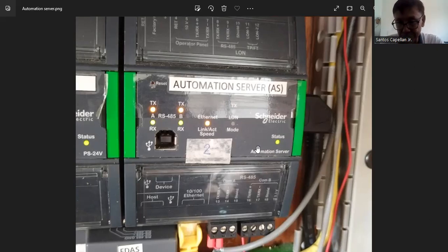Then down below, it is capable of communicating to, let's say you have a COM-A here for BACnet controllers like my B3 devices based on my previous tutorials. Then for third-party systems like this thermostat, DDCs, let's say chiller plant manager, which is also working in MSTP. Okay, so this is a very powerful network controller.